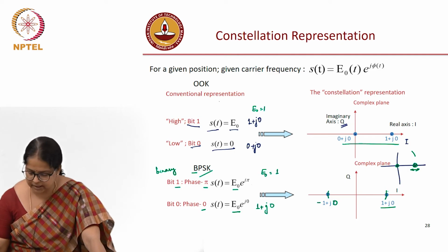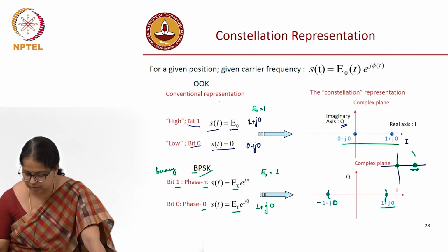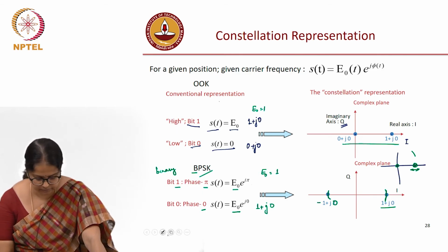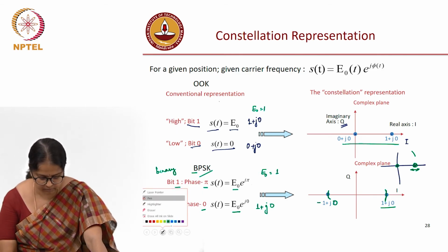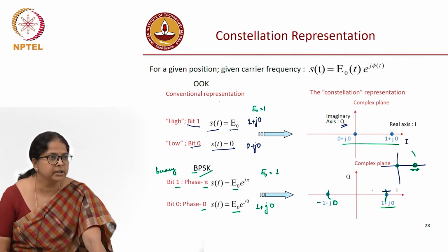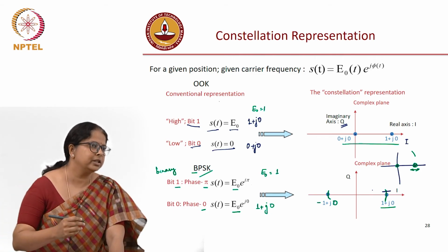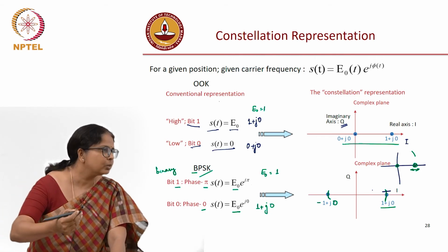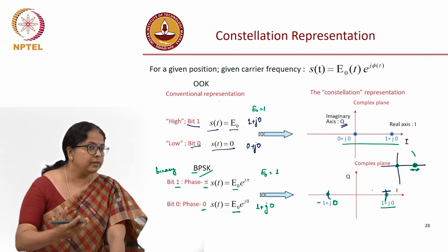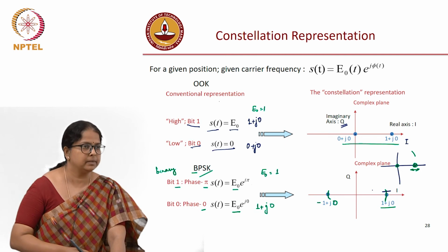You understand that error in phase will appear as an angle, error in amplitude is going to appear along the horizontal direction. This is going to be useful later on when we talk about signal to noise ratio, and as you are increasing noise, what does an EDFA or an amplifier do to the constellation. We will talk with reference to the constellation.